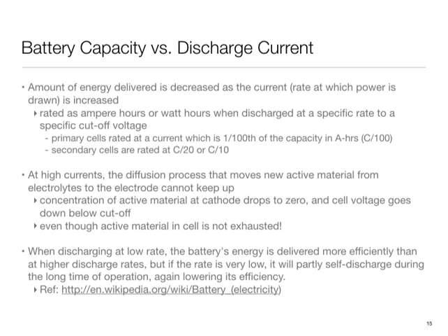So on this issue of battery capacity versus discharge current, intuitively what is happening inside is the following. When a battery supplies current, essentially what's happening is the ions inside the electrolyte in the battery are moving. And that's a physical process governed by laws of diffusion. Depending upon the diffusion constant, there's a rapidity with which this process can take place. So when I draw a large amount of current, more charges have to flow. So I'm putting more demand on that diffusion process, and it cannot keep up with it. So what happens is that inside the charges are moving to the terminal sluggishly, but I'm consuming them very rapidly. So the queue of charges near the terminal becomes empty, to use that analogy. So even though there is material inside the battery, I just suck them out so rapidly that there is a paucity of it near the terminal. So the battery dies quickly.